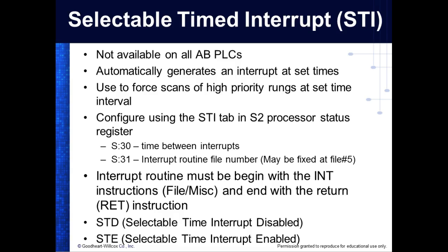We'll see if they're on the 504s. Anybody on the 504s? All you have to do is look at your instruction set on the top and see if these interrupts are available. I know they're not available on the 1000 because I just brought up RSLogix with the 1000. So not available on all PLCs.